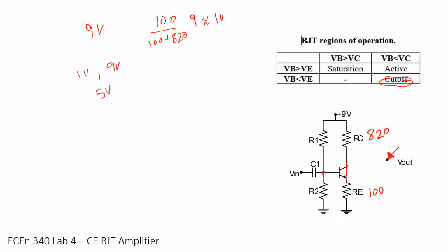So now we're going to think about the voltages and everything involved. This guy here, we think of it as functioning pretty much like a diode, and let's say it's 0.5 or 0.6 or 0.7, some amount of voltage drop here. So I'm going to say 0.6. I need to know my current through here, because if I know this voltage drop plus my voltage drop across here, then I can know the voltage that I need here, VB.